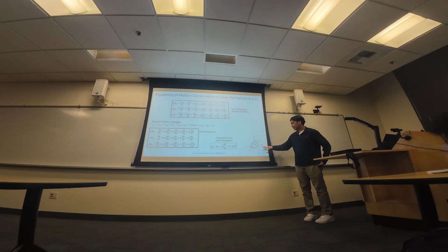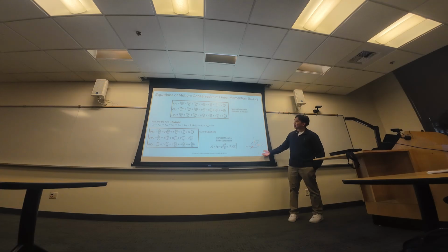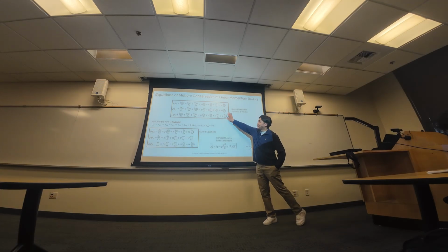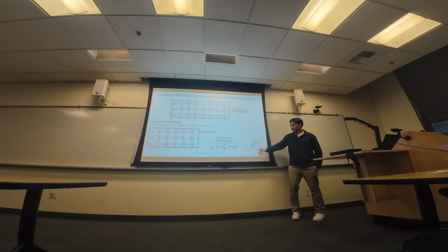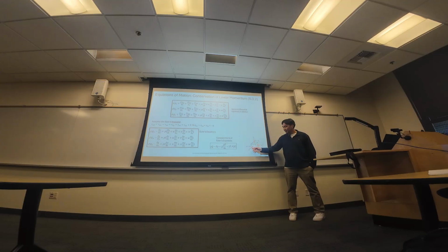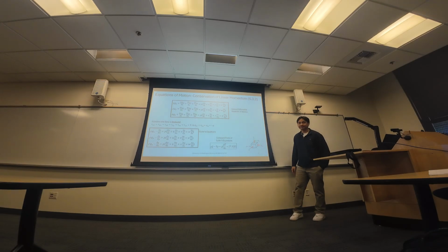And like I said, how you read these, again, two subscripts xx, that means you're working off the x-axis in the x direction. This is important because if you try to do something up here, you need to know how these directions work. If this is x subscript y, you're following the x direction, but your force is going in the y direction, which usually means shear stress. But in this scenario it won't matter because you assume your shear stresses are 0.